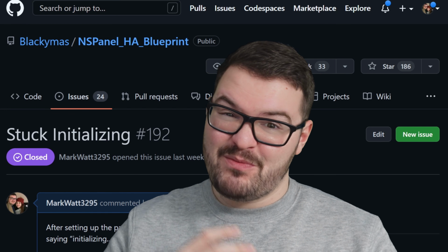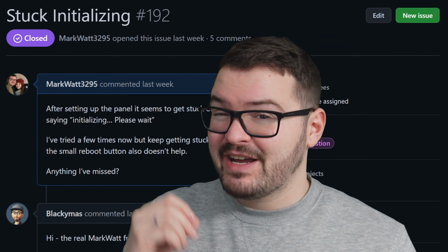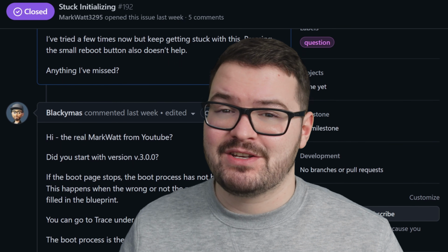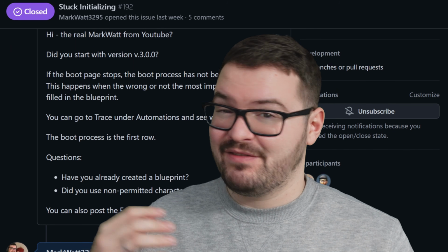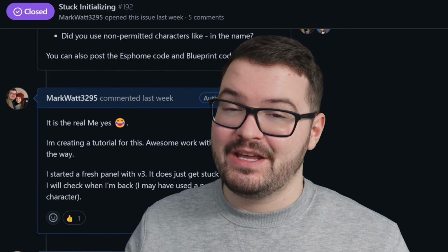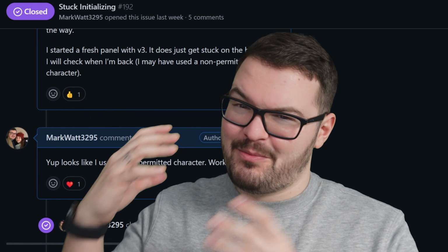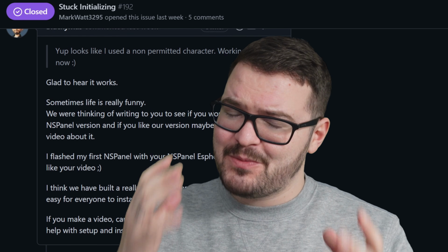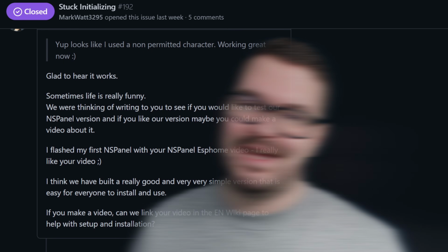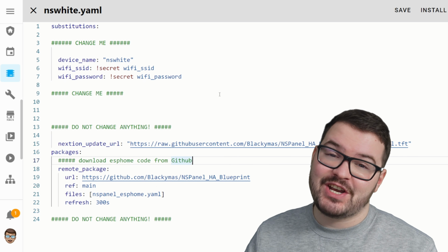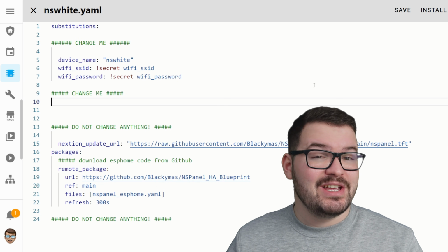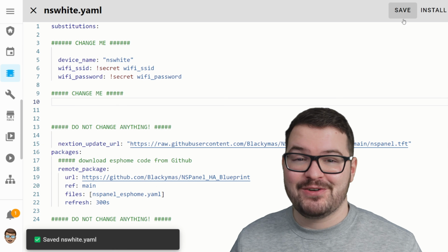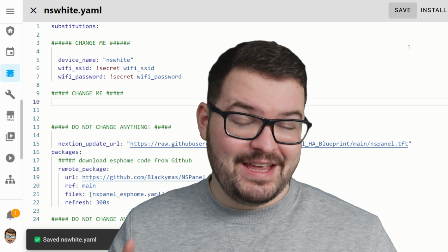One quick tip here to hopefully save you a little headache is your device name can't contain any special characters. So the first time I did this, my device was called NSPanel-White, and that dash caused me to not be able to actually load the full configuration onto my NSPanel. So don't include any special characters in your device name. Once you've made those changes in the Change Me block and you're happy that they're correct, you can just go ahead and press save in the top right corner. And that's literally it for the ESP sketch.